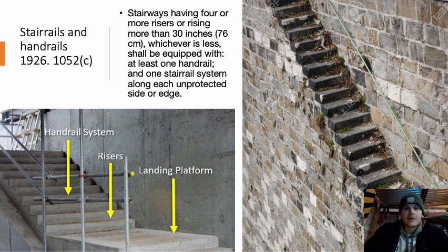All right, and then on the right photo, I'm not really sure if this is on a construction site. It's what pulled up on Google. But you can tell that it has one little handrail for the protected side, excuse me. But on the unprotected side, which obviously falls off very far, there's no stair rail or handrail. So we do not want to see anything like this, or anything that looks unsafe at all.